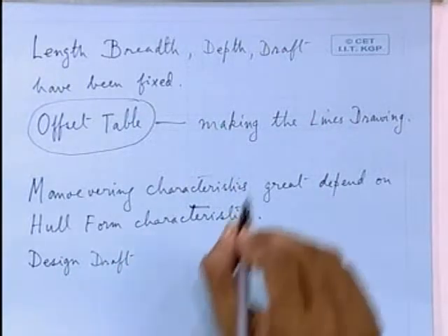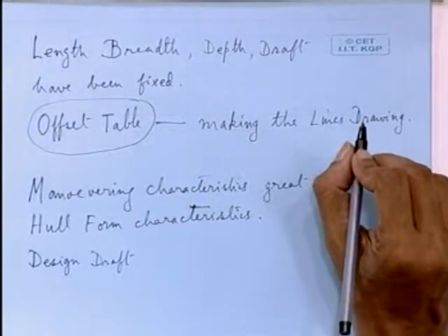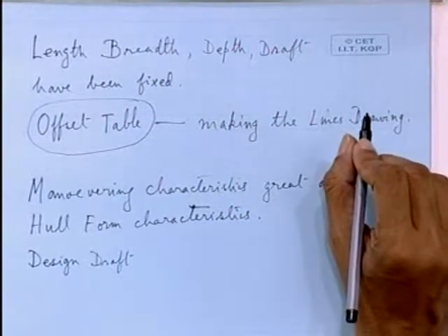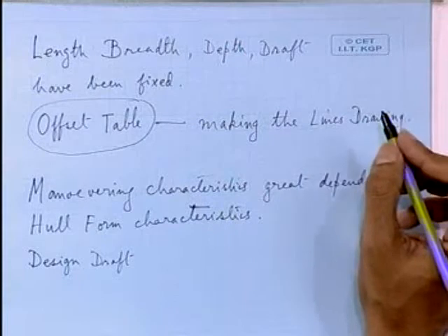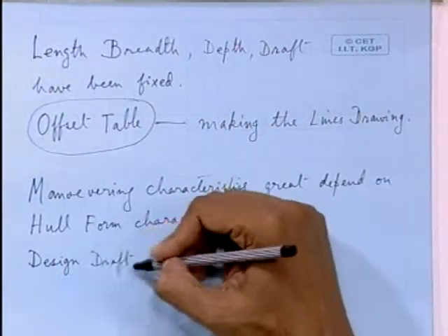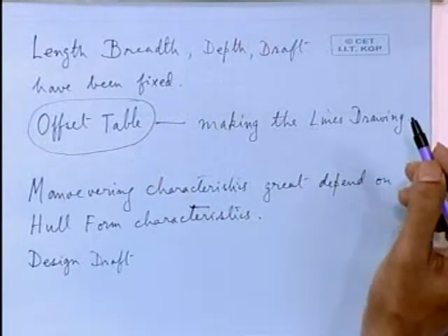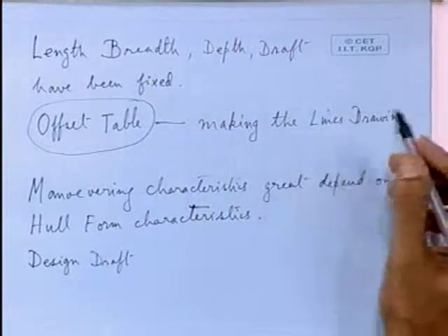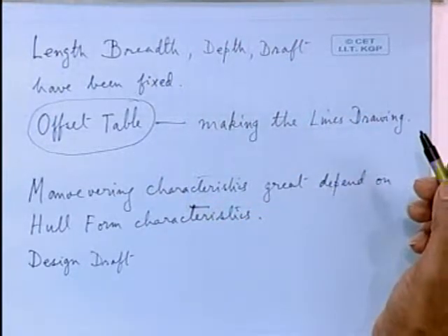That is the maximum draft, or maximum immersion, at which the ship is to float. That is, the ship should not sink. And if this draft criterion is not satisfied, and the ship steams at a greater draft, then there is some penalty.